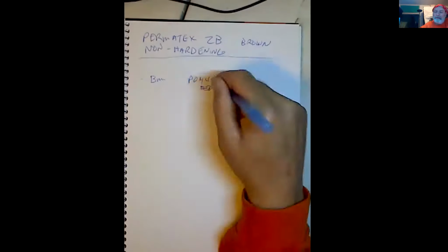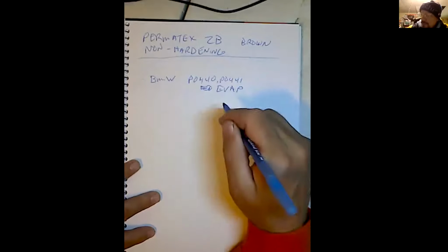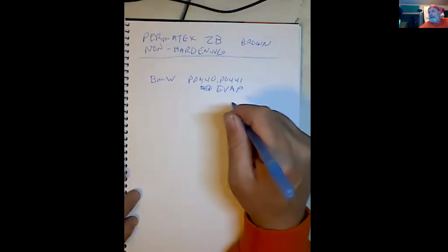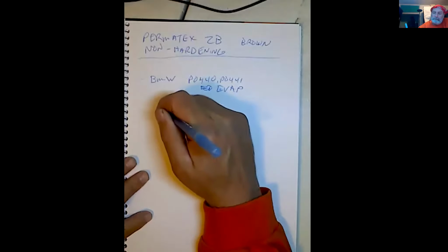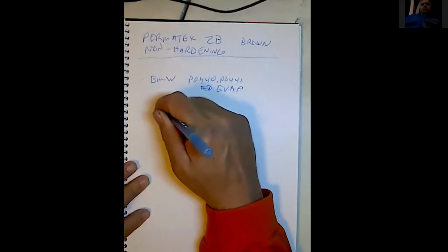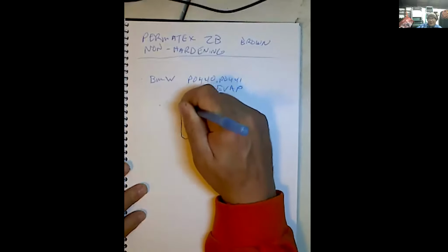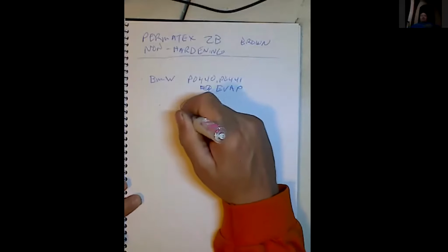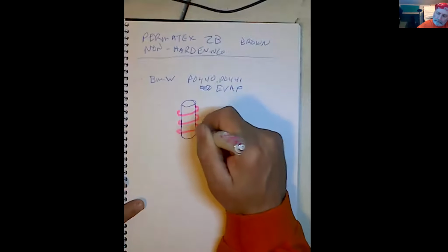Well, the first one causes the second one, right? Oh, okay. 444 causes 441. No, the open in the purge control valve is what causes the purge flow to be incorrect. Is that true, Chuck? Yes. That valve opens under certain conditions to relieve the gases from the canister, or at least it's supposed to. It's not RPM, it's certain enable criteria. Right.